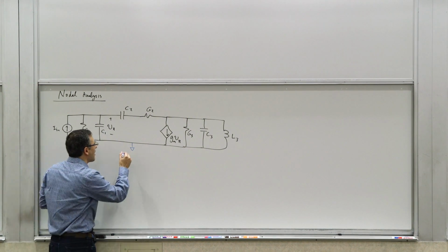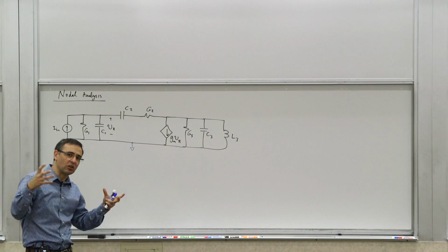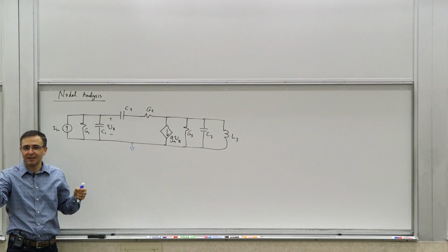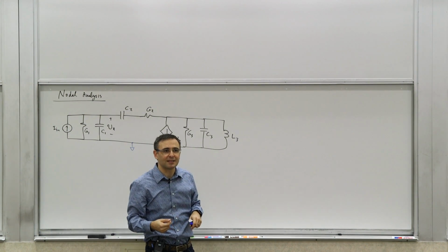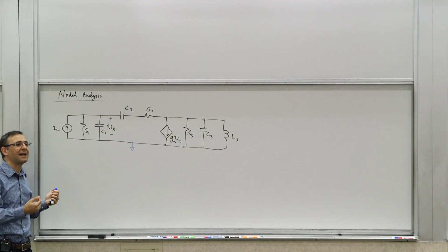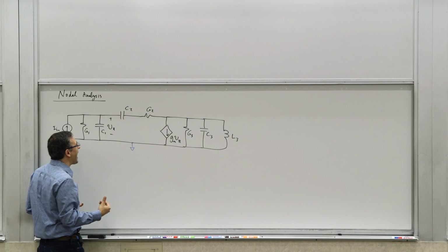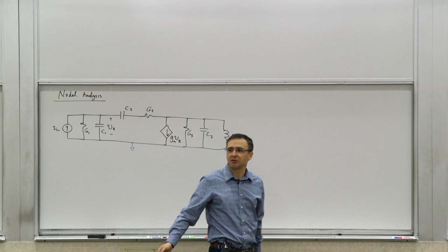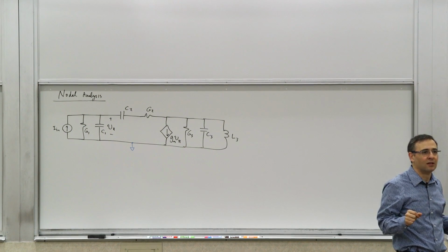This is zero potential. Now, this is not necessarily true from a physical perspective, in the sense that if you have a large physical circuit, different parts may be connected through a piece of metal, but that connecting metal may have resistance. There may be inductance, there's capacitance to ground, there are all sorts of other parameters. And that means you have to differentiate between a mathematical abstraction and a physical model. If you are, for example, in the lab, you may have everything connected to some big sheet of metal. So that's my ground. It doesn't mean that every point on that ground will have the same potential. So you have to think about it.